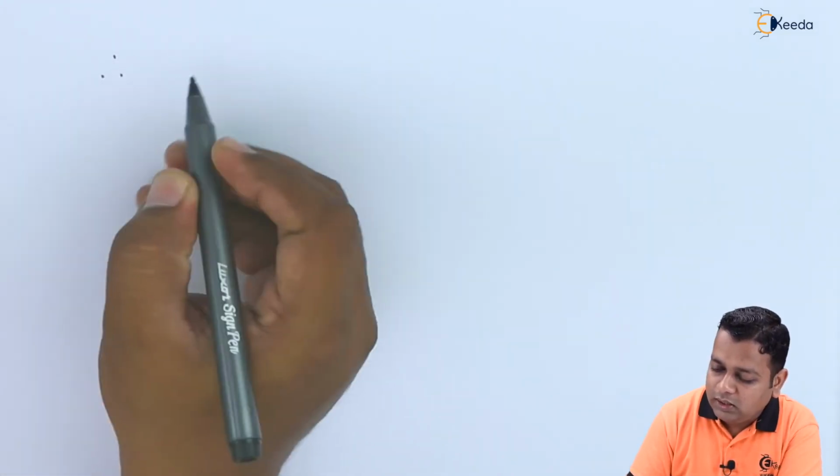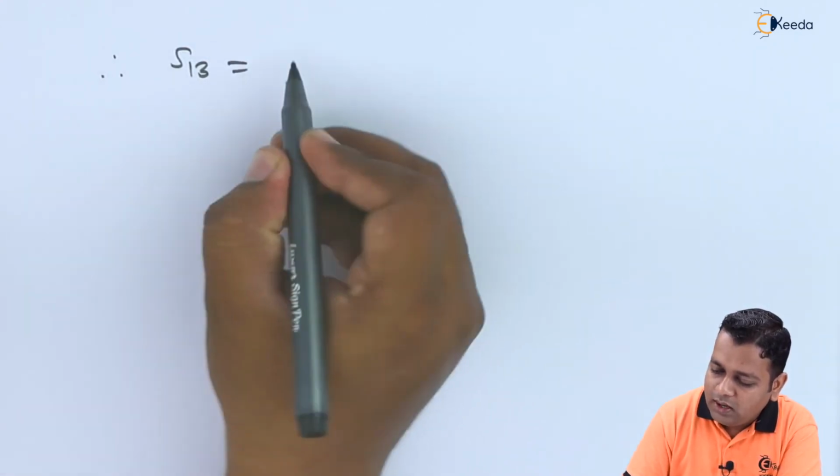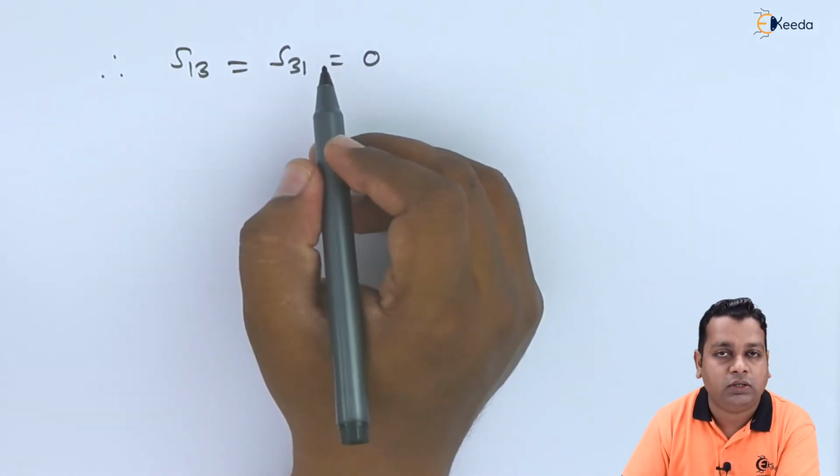Now in addition to that, as we know the structure of the directional coupler, the pair of ports, port number 1 and port number 3, are isolated ports, whereas the pair of ports, port number 2 and port number 4, are also isolated ports. So we can make the scattering coefficients S suffix 13 and S suffix 31 equal to 0 here.